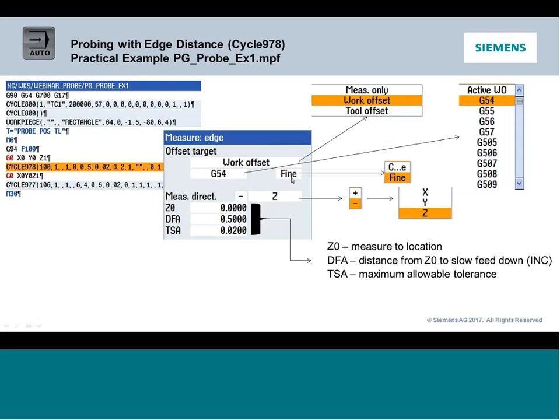Now you have a couple options of how you want to write. So you can write to the coarse field or the fine field of the offset. So we're going to go in, you're going to look at the offset table. You can see how we have two different areas that we can use on work offsets. Fine is kind of like an incremental adjustment. It will add into the coarse field. So if I'm doing a modification of a coordinate, a lot of times I like to write to fine because maybe my original coarse one's still valid. And again, we're just picking up some inaccuracy in maybe the loading process. So why have to delete that offset every time? If I know that the first one is just a rough offset to get me close, then I might want to write over the coarse. So that's just a matter of selecting the coarse or fine field.